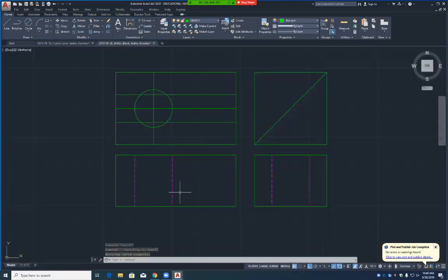Right, but that inch is measured from where this 1/2 inch is down here, right? It doesn't say it's symmetrical around this, it's measured from that 1/2 inch down, right? I mean, when it's milling, when the machine bit goes through, it's going to be 1 inch. Well, even the 1 inch is going to have a tolerance. I'm saying when it's machining, it's attempted to be machined at 1 inch, but it won't be exactly 1 inch. That's right.